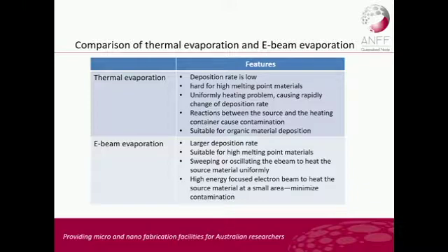Another concern for thermal evaporation is contamination, because you are heating the container, which is the boat, and the source together, so it may cause contamination from the boat. But one good thing about thermal evaporation is that because the rate is low, it's good for organic material deposition.